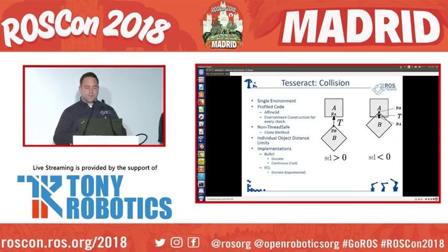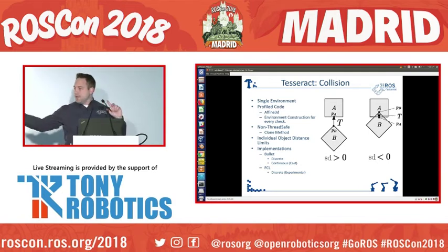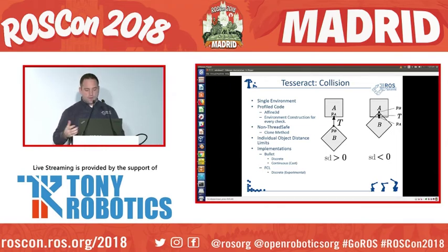So you still need to discretize it, since it's more of a linear approximation of your actual motion. Say your arm's here, and then your arm's here, and you say plan a motion, and you have an object in front of you. It's not going to see that, because it sweeps the volume from left to right. So you still need to divide up your path such that you can take advantage of this. And then we currently have FCL implemented for discrete collision checking.